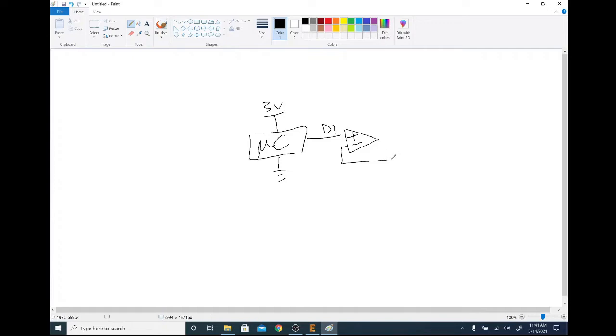We're going to set this up as a constant current supply. So we have our current limiting resistor down there. We have a transistor up here, and that's an N-type transistor. And then we're going to have our 2 LEDs that we want to drive sitting above the whole thing. And those will be powered by a 6-volt as well as our op amp here. The op amp is going in single supply mode, so that'll be at 0 on the negative supply. And then this transistor that we're using is the 2N3904 transistor. And that's our whole circuit.